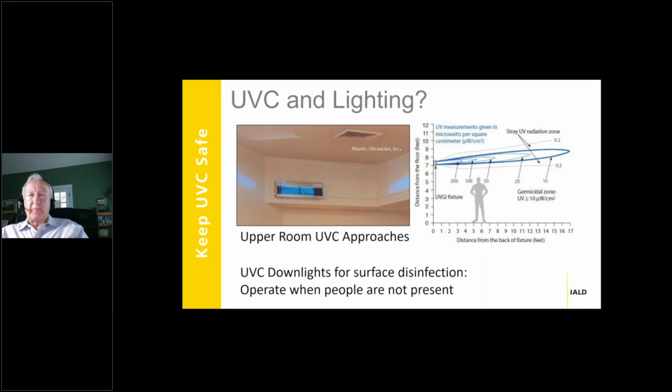And that's typically why UVC systems are used to illuminate ductwork, in some cases to purify air going into rooms. It's also used to disinfect the upper air inside of a room where specialized optics or reflectors are used to shine UVC radiation back and forth above where people are for disinfecting air in different spaces. But you don't want to really shine UVC radiation on people at all.